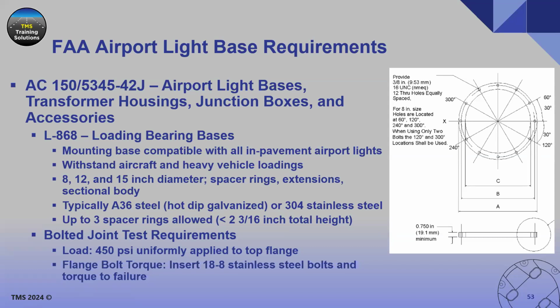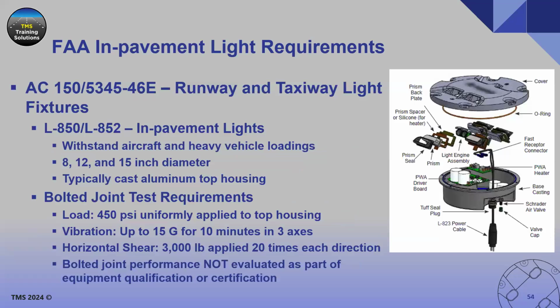And then the other one is the flange bolt torque test, which uses 18/8 stainless steel bolts, and you insert them into the tapped holes in the flange and turn them until the stainless steel bolts fail. And the point there is to check for any damage or deformation in the threads that are formed inside the top flange. Next. Then the other major component is the light fixture itself. So on the right, I have an exploded view of a typical in-pavement light fixture.